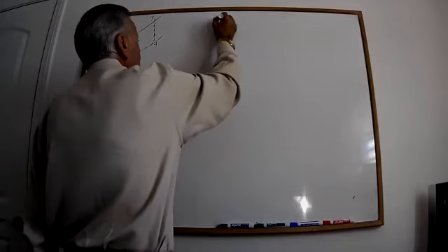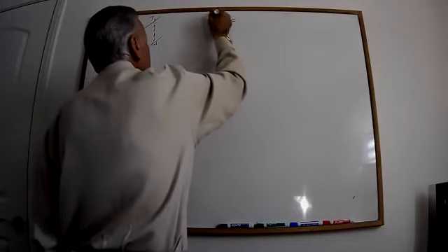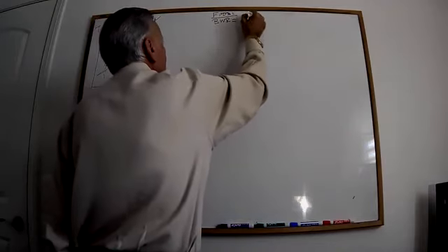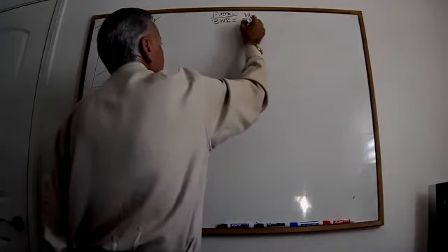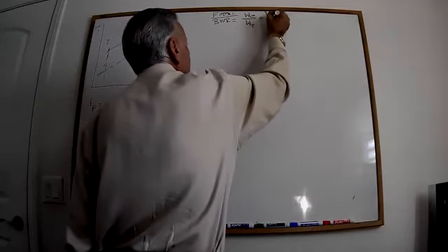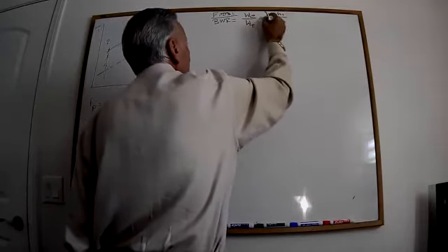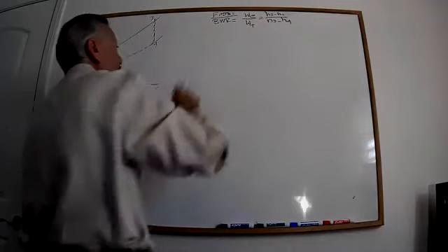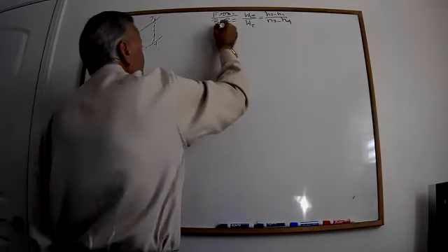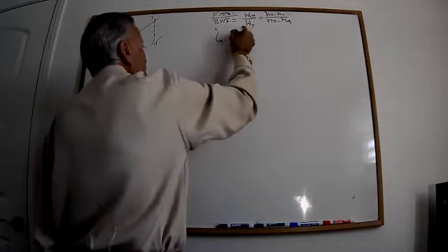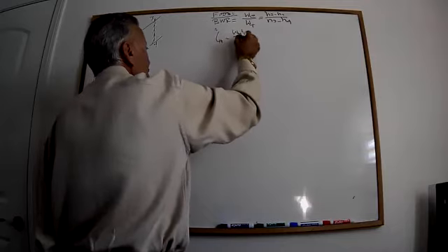The backwork ratio, this is what we need to find, is work of a compressor divided by work of a turbine. Work of a compressor is H2 minus H1, divided by H3 minus H4. That's what I need to do. Thermal efficiency is net work divided by Q in.